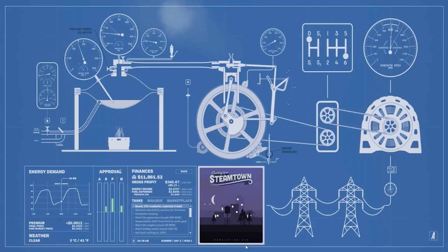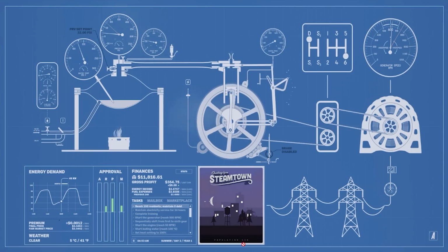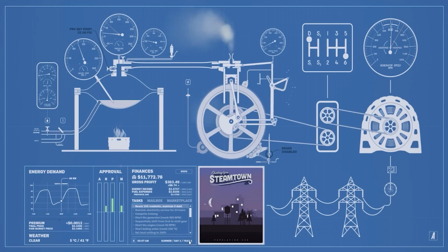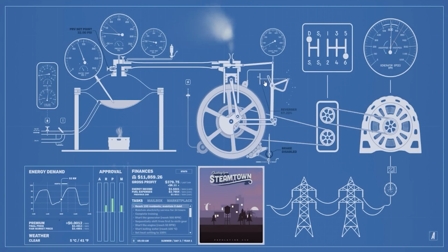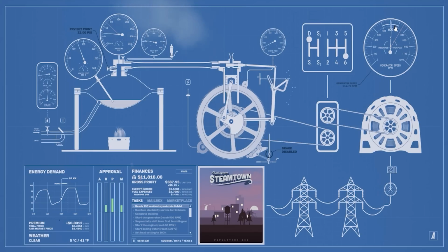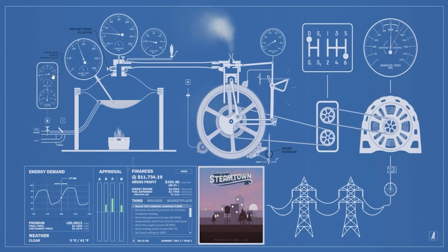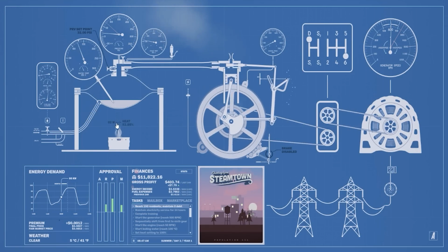Okay, 128. We're on summer, day 2, year 1. Good. I think I can alter the reverser a little bit. Like so. Just to slow that down because it was overspeeding a bit. But subtle steps, small, meaningful changes where necessary.